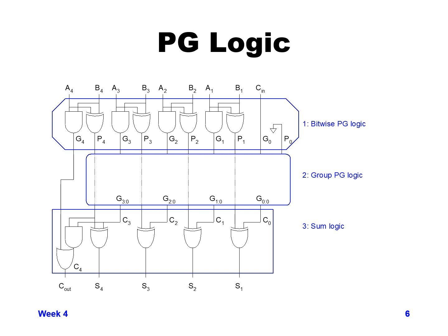and then based on that you get your carry out 0 through carry out 3. Finally, at the bottom you see the sum logic, which depends on the propagate for each individual bit and then the carry bit to come through the PG logic in order to generate our sum.